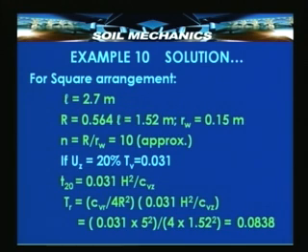That gives us the time taken for 20% consolidation as some value, and the corresponding time factor as 0.0838. Now, what am I trying to do? I know that the vertical consolidation without sand drains is 20%. What I am trying to do is, I am finding out for that vertical consolidation what is the corresponding Tv.